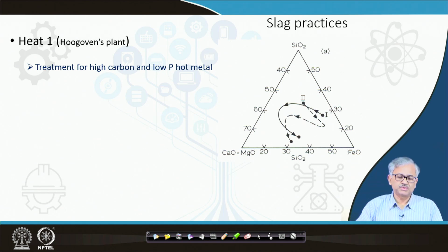In Indian steel we have phosphorus percentage from 0.1 to 0.4 in this range somewhere, and some very high phosphorus steel is also there in European countries, where the phosphorus percentage may be even greater than 1%. Here we are talking about a very low one, and in Japan the hot metal also contains a lot of low phosphorus hot metal, right.